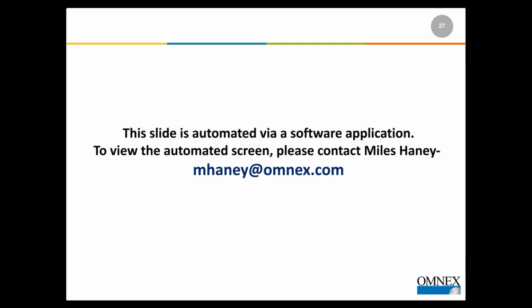So when you draw this as a block diagram, you can actually automate the interface functions and say speed sensor to ECU interface function, front cache sensor to ECU interface function. So those actually will get populated automatically into the DFMEA.